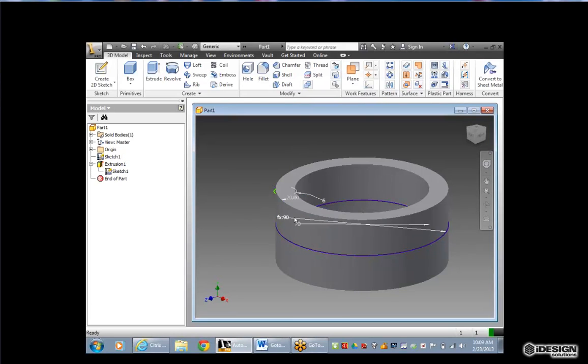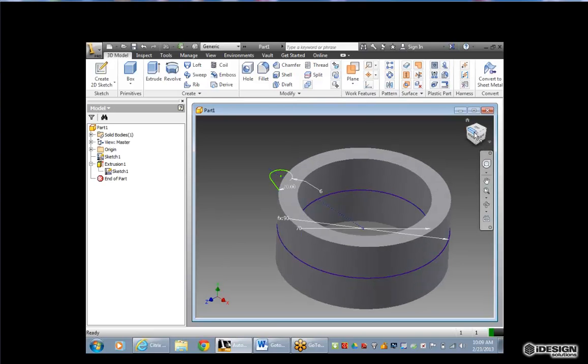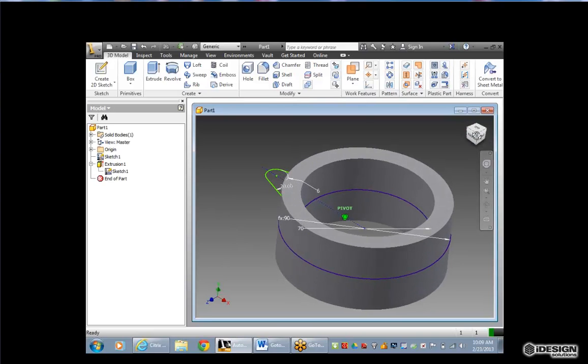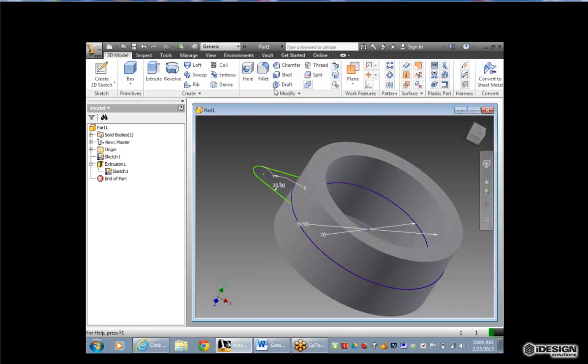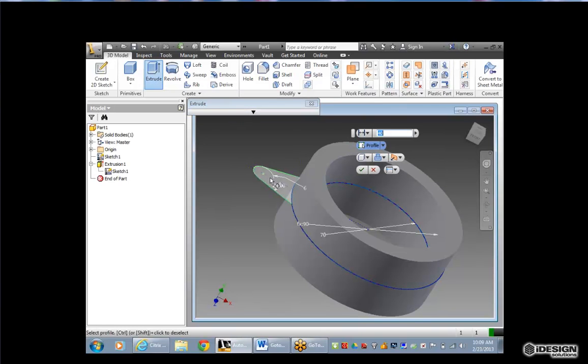Okay, so now we'd want to use the view cube so we can see that other profile, and then just apply that next extrusion. Okay, so extrude, and boom, to this. And we did symmetric, and I think you said 12. Yeah. And boom.